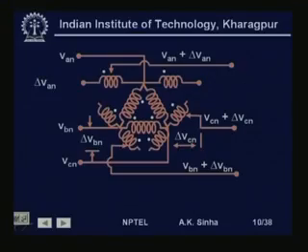Now, the same thing if we do by injecting voltage which is not in phase, but in quadrature. If you look at this transformer, we have a transformer here like this, which is connected to the primary 3 phases AN, BN and CN at these points. We have another winding which has half on this side and half on this side, that is, the midpoint is connected to this point A, and this winding has the phase of BC.